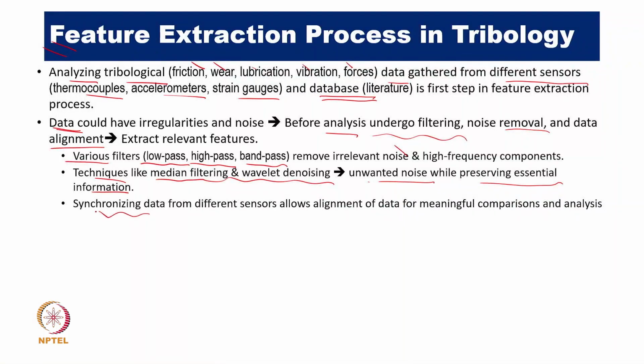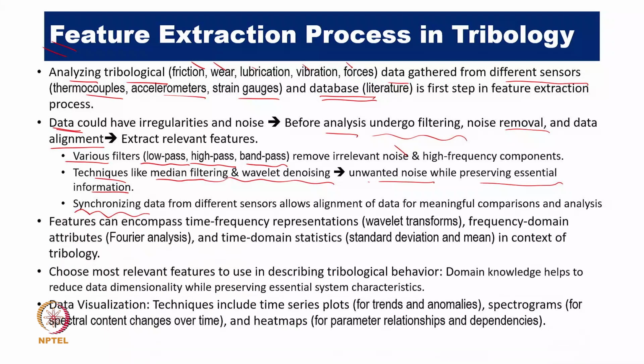As I mentioned, synchronization is important, and I'll be elaborating on that in one of the slides, which will be discussing the gear case. We say the features may have variations. We can have a time frequency representation, a frequency domain representation, and this is what I was mentioning: the low pass frequency, high pass frequency, band pass frequency. Often we connect with the frequency domain attributes. We also have time domain statistics, where we go ahead with the synchronizing.